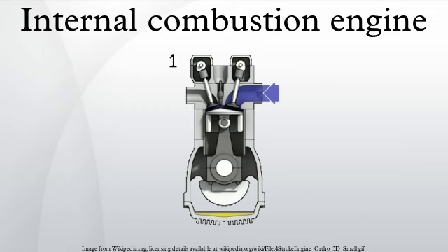While it is true that 3 power strokes typically occur per rotor revolution due to the 3-to-1 revolution ratio of the rotor to the eccentric shaft, only 1 power stroke per shaft revolution actually occurs. This engine provides 3 power strokes per revolution per rotor, giving it a greater power-to-weight ratio than piston engines. This type of engine was most notably used in the Mazda RX-8, the earlier RX-7, and other models.